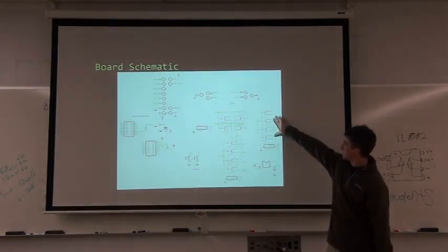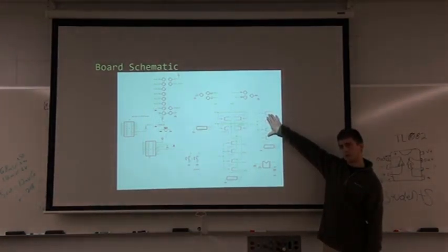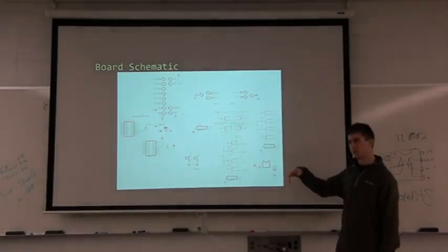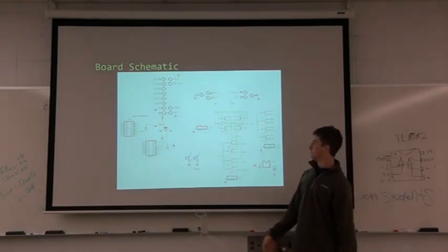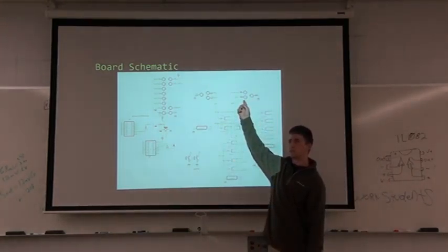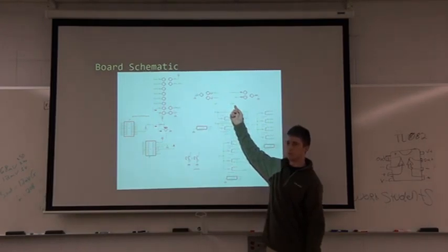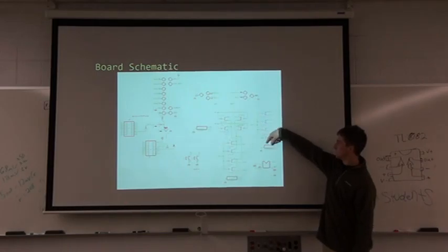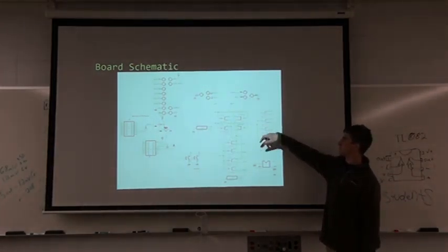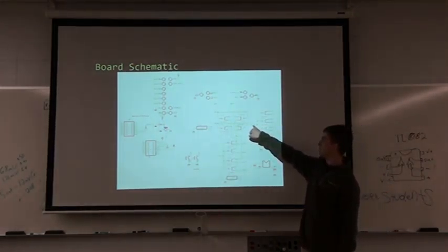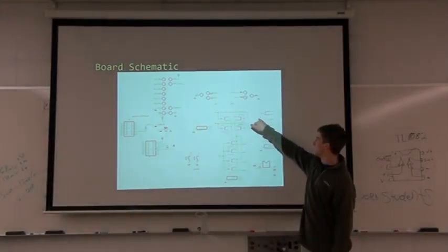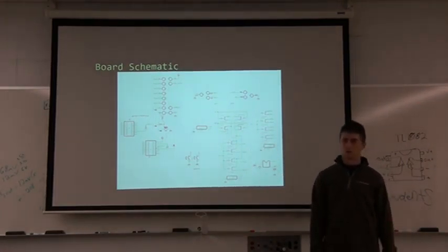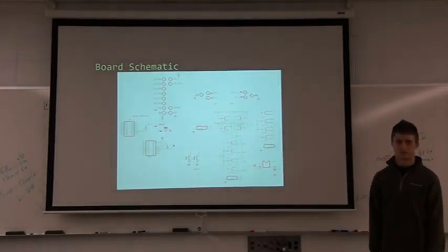This is the switch set for the radio, so that it'll just get switched through when there isn't any signal input or a user hasn't selected the input for the auxiliary. And so since I don't need all these to be individually controlled, I can just control them with one pin. And so I just tied them all together on the board and just controlling them with one pin from the micro. And the currents are so low that it'll be fine.